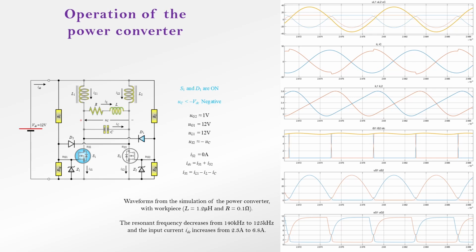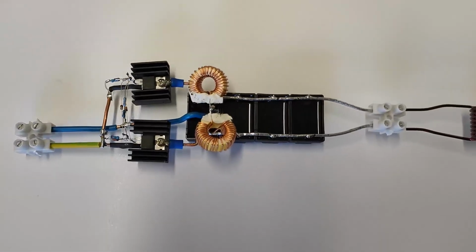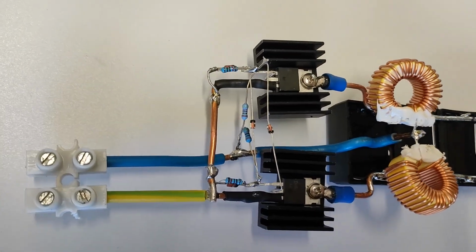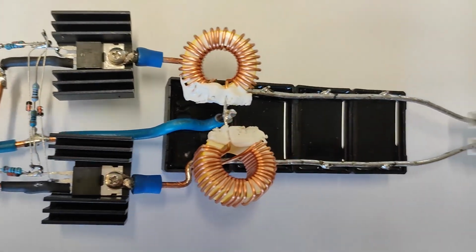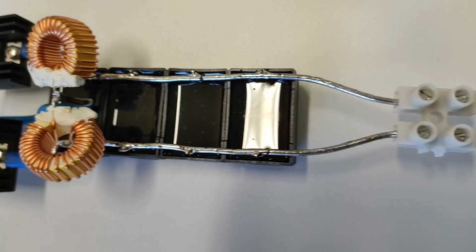According to the simulation, the currents in the parallel resonance circuit are extremely high. As a result, capacitors with special specifications are required. Furthermore, the overall circuit assembly must take these very high currents into account.